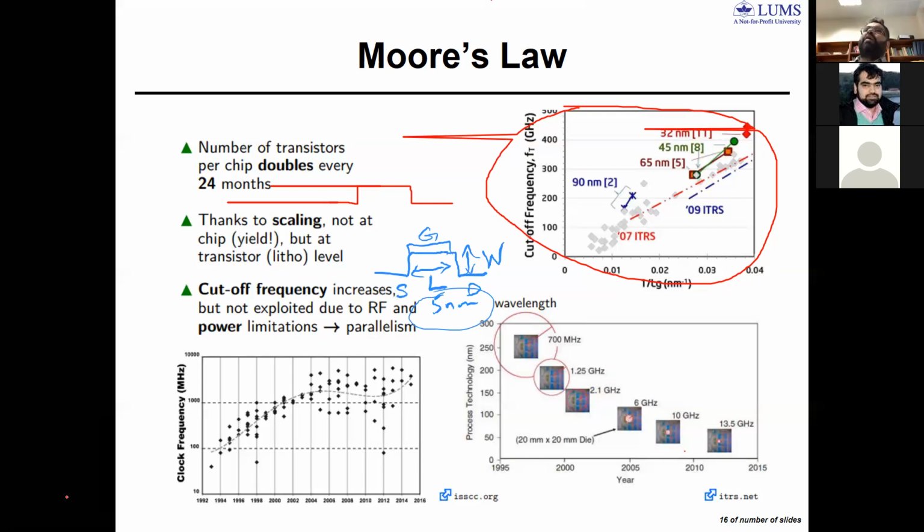So in analog, we still use 45, 65 nanometer, 180 nanometer. It's not like we cannot create circuits at a smaller level, but there is no benefit of going for 5 nanometer for analog circuits. We will describe this a little in the context of the course, but that comes under the advanced category. Normally, in analog, since we use resistors, capacitors and inductors, those things don't scale down.